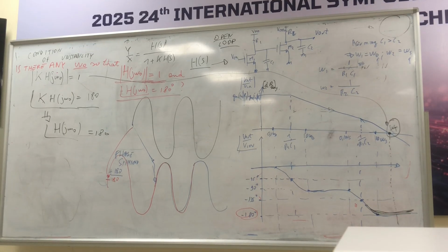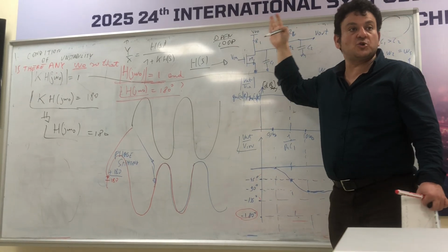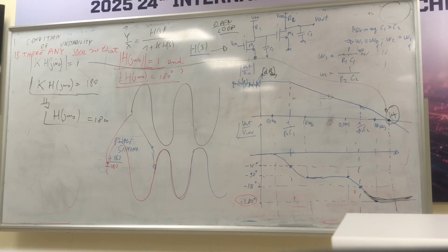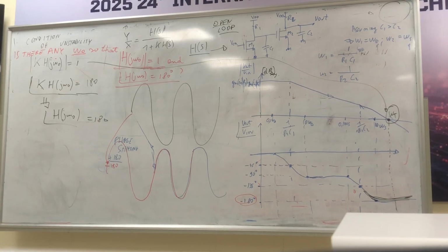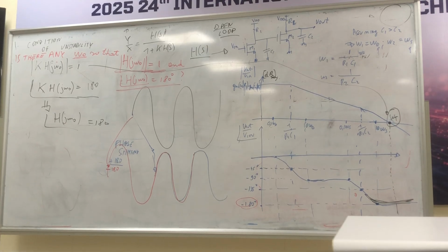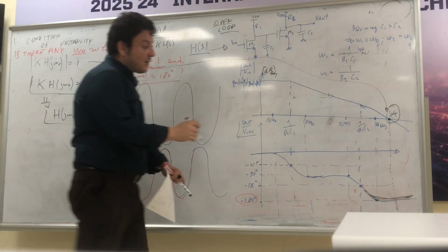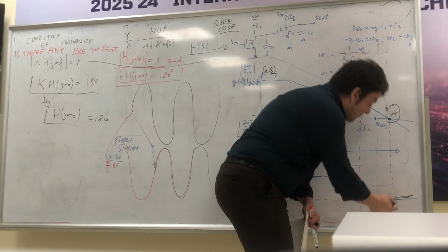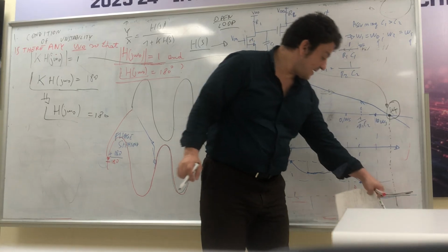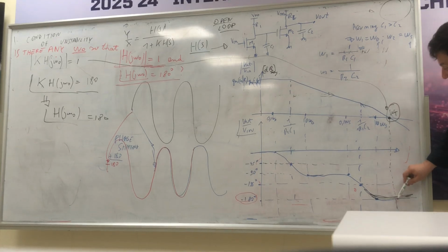In practice, I'm really scared that if I just place a feedback loop, this network could go into instability, because here is very close to this value, okay? So actually, what I need to do, if you just look at this network, okay? I want to be as far as possible from the value for which my transition frequency has a corresponding phase equal to 180.